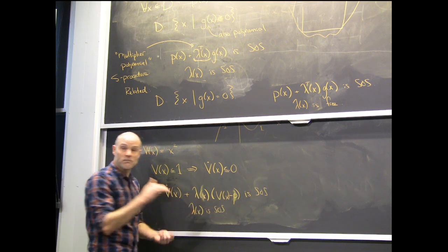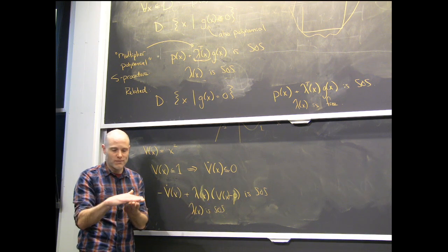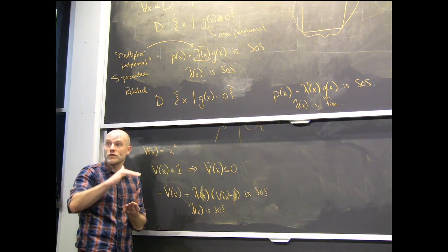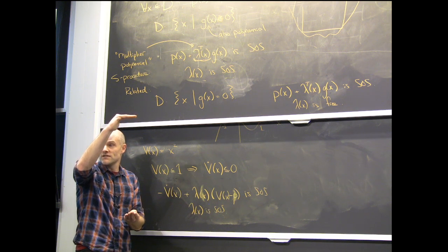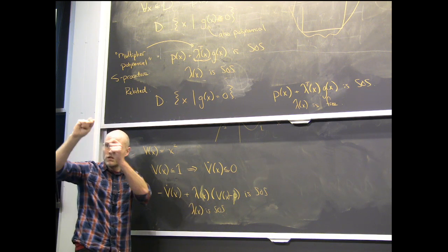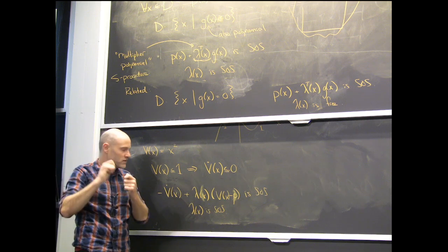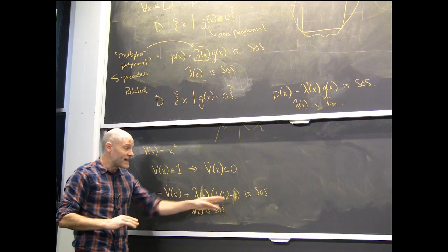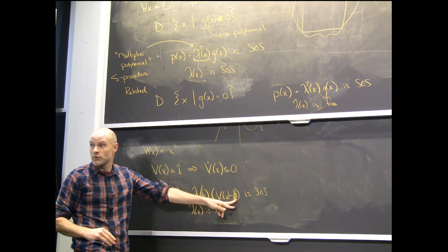If I pick a very small value, as long as it's locally stable, I would expect it to eventually pass. Then if I start increasing rho, it will eventually fail. Turns out there's a nice monotonicity property there, so you can just do golden section or branching search. So you can do a line search to find the biggest rho to find your region of attraction.